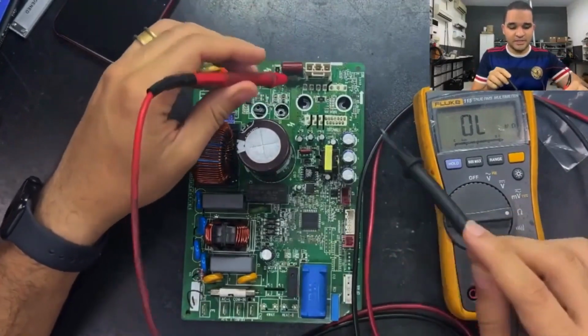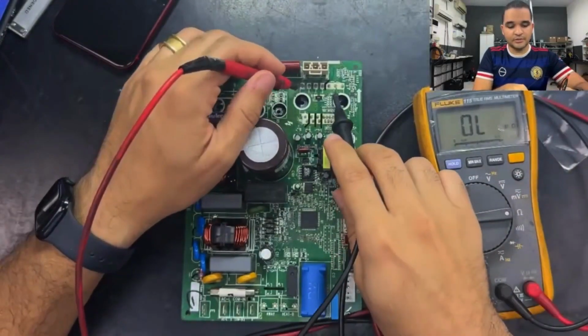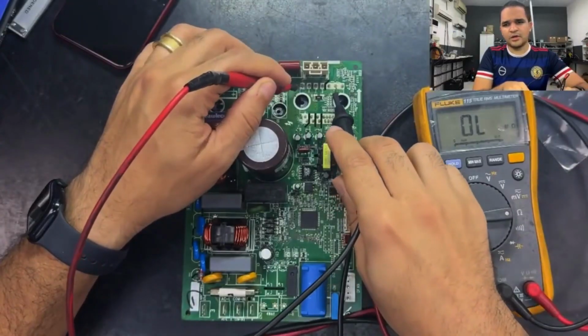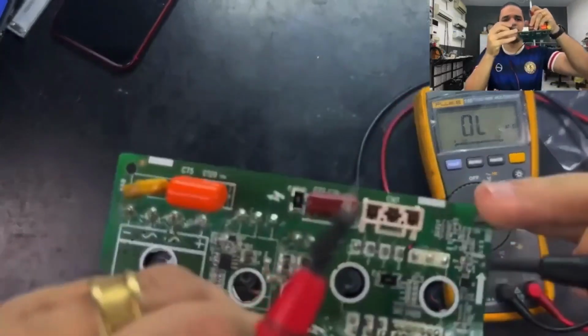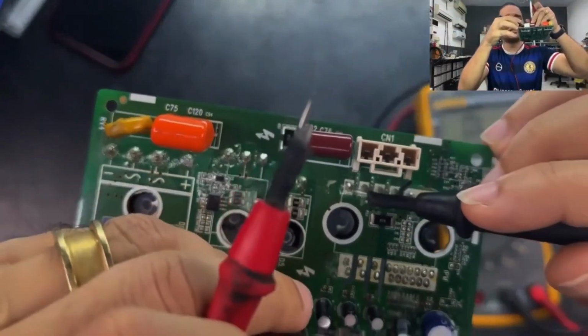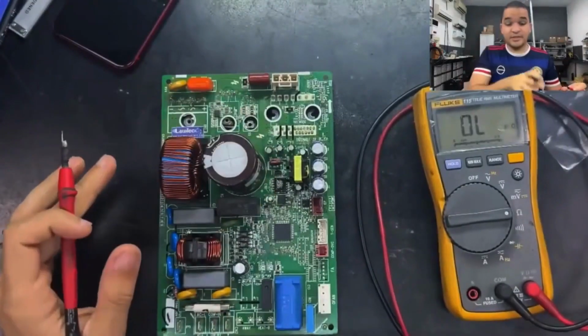The measurement that you're able to perform on the DC protection board involves measuring from this particular point to that specific point here on the IPM, obviously with a great deal of care, correct? Simply measure from this location to that location, from these 3 points here that are grouped together to this single one that stands alone, all right? Then I have 310 volts.